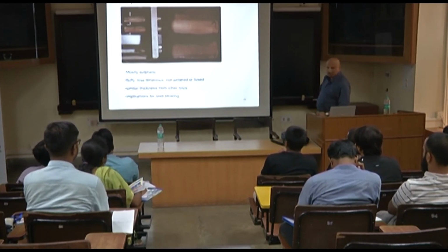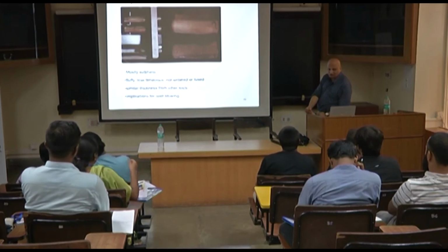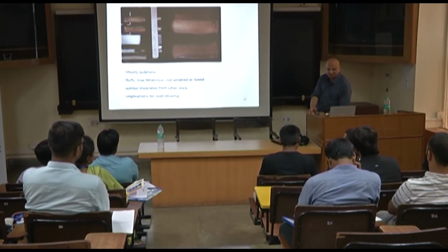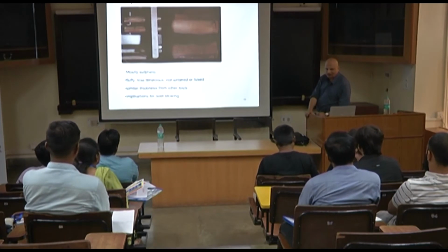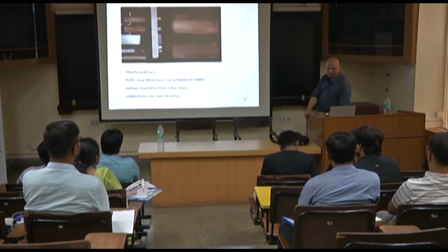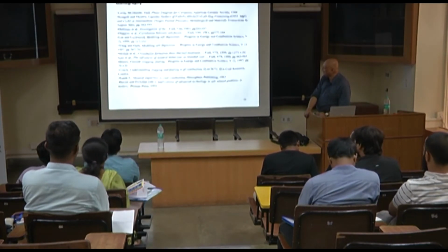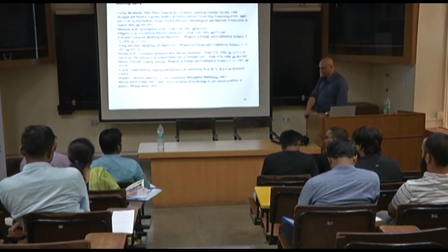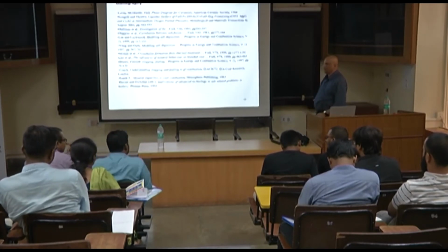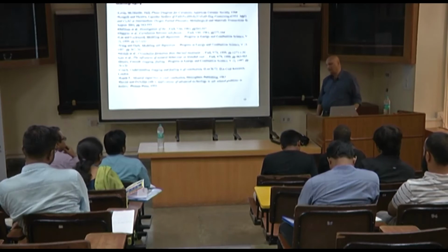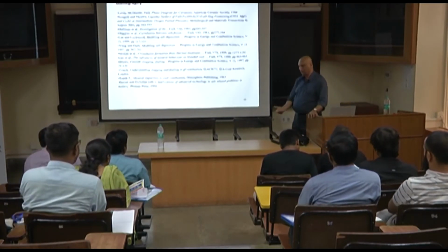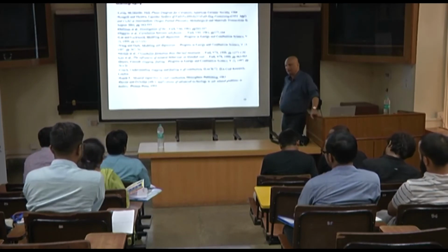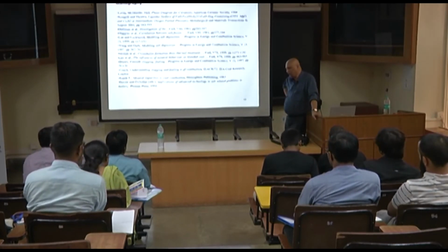So the deposition that happens is a function of the coal ash property, temperature, environment, and of course time. If you don't do any online cleaning, if they sit idle, of course they will build up, and then it will create an unmanageable problem. And if you look at the ash analysis, ultimate analysis, together with the sodium and chlorine, then you can easily say that this coal will not be problematic anyway.